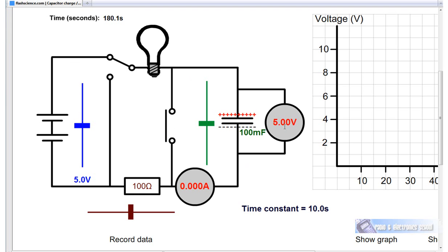Now if you watch the voltmeter and the ammeter, when I operate this switch, you'll see the discharge current through the ammeter, and you'll also see the voltage on the voltmeter dropping all the way down to 0 volts. So let's do that, and there's no resistor, so that will happen very quickly. Didn't even see the current dropping. I'll just stop that again, because as soon as I let go, the capacitor is going to charge.